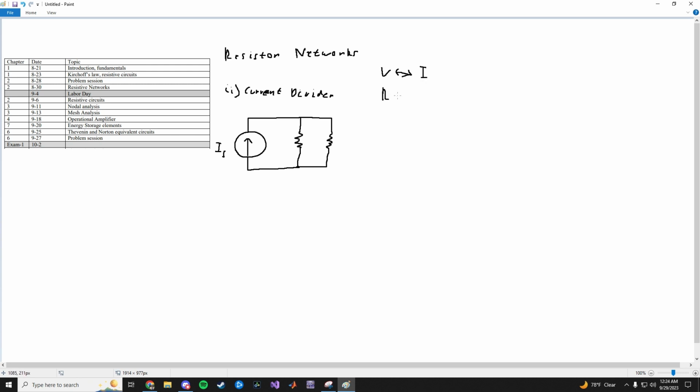And then for resistance, the dual, well, you can imagine it's going to be the conductance G, which is 1 over R, just the reciprocal of R. So for this current divider, we were going to use the KCL instead of the KVL. That's another dual. The Kirchhoff's voltage law, or the loop law, and then there's the KCL, the dual relationship. So this current flowing to this node is going to be the unknown voltage V1, and then the ground reference, I'll choose it to be here.